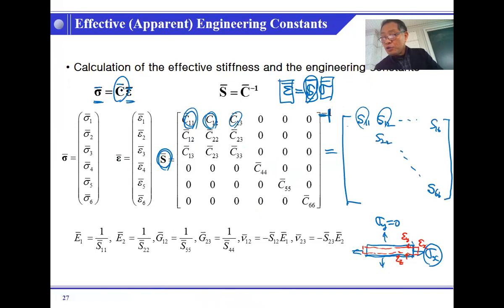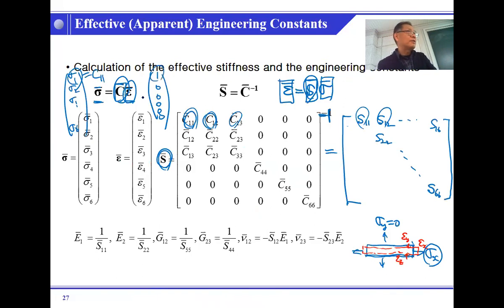Why? Well, to measure the stiffness, I mean the C matrix, we need to apply, for example, 1, 0, 0, 0, 0, 0, right? And then whatever you get, the stresses will be sigma 1, 2, 3, and so on, up to sigma 6. And these will simply be C11 because we are applying one component, any terms, right?